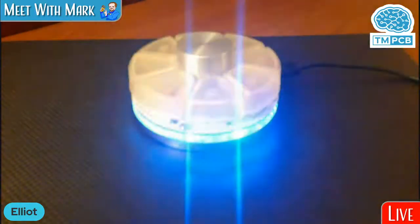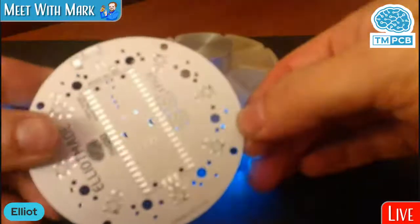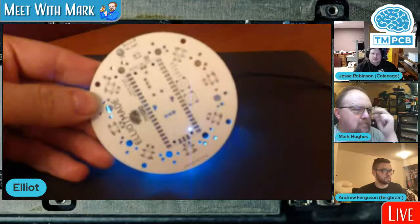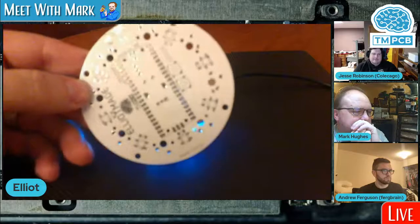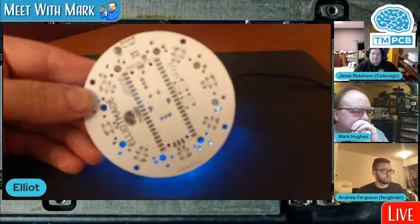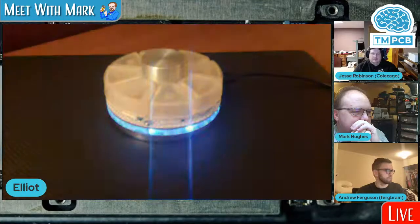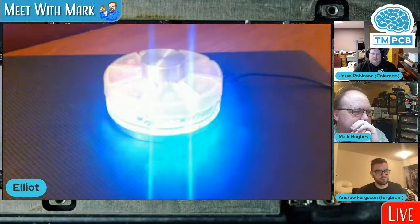Are the LEDs going into the acrylic? Is the acrylic in a ring that's open in the middle, or is it flat? It is one piece, and this top one is also out of focus. What I did is I cut out clearance all the way through the acrylic everywhere there was an LED or another component. So it has a cutout where the Pico is, a cutout for the switches, a cutout for basically everything. It looks like a ton of holes, and then it's just a continuous edge around the outside, which makes it kind of into a giant light pipe. And did you print those keys yourself? I did.